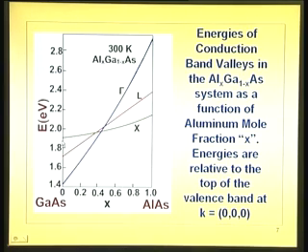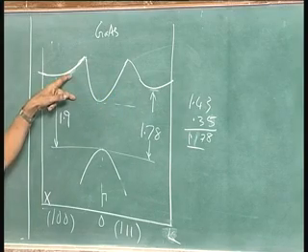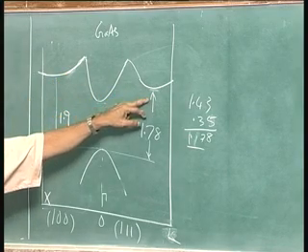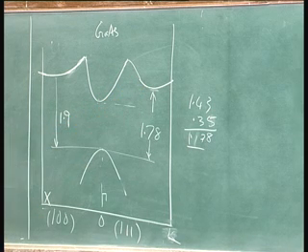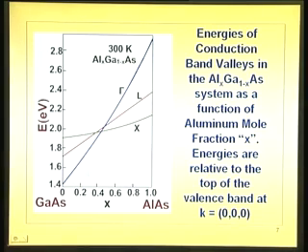But in this case, aluminum arsenide also, you will have direct, which is 3.2, and if you vary x along the 1 0 0 direction, that band gap will vary from 1.9 to 2.17. So, we were looking at actually 2.17 only, and we are looking at this somewhere here, join them together.